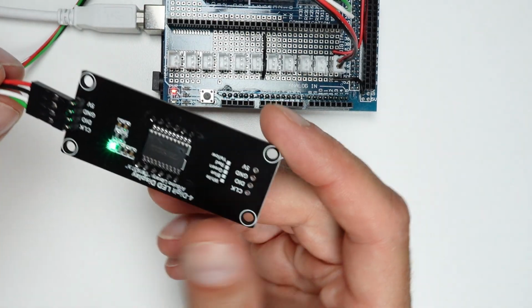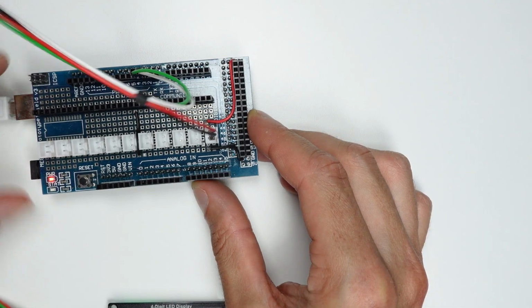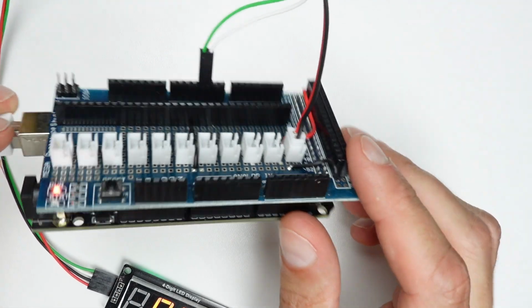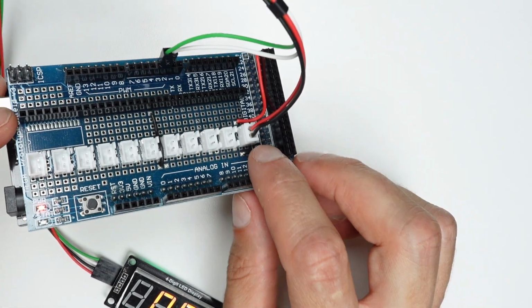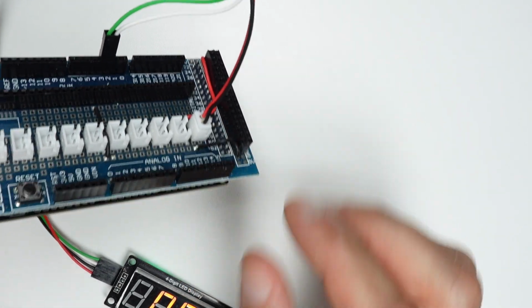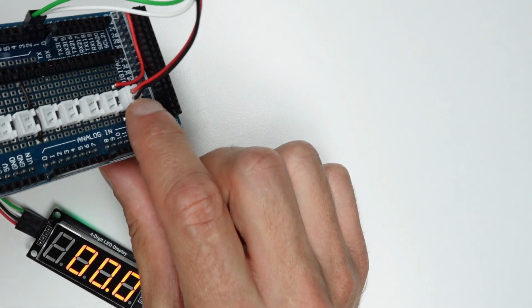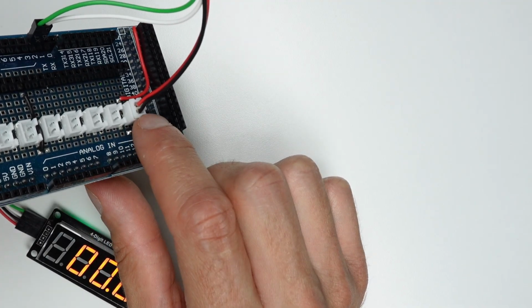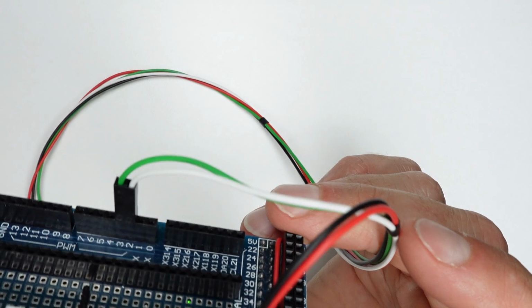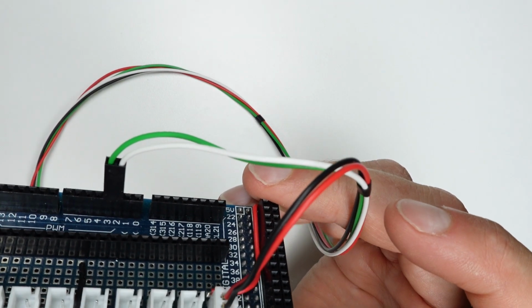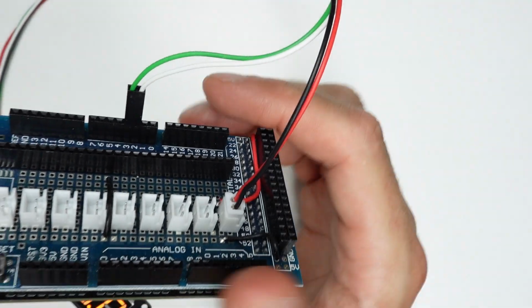So this one is connected with a 4-pin DuPont connector to the Arduino. Here on the Arduino, I'm using my expansion board from one of the last videos. I will provide the 7-segment display with power from these sockets, and then it's connected to pin number 2 and 3, the data and the clock pin, and we have to assign it later in MobiFlight. That's how easy it is to connect the 7-segment display to the SIM.